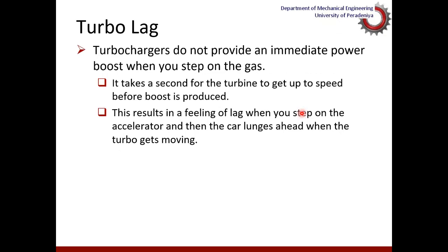And one of the issues with turbocharging is the turbo lag. Turbo lag is more or less the delay in response. Now, these turbochargers or superchargers are made using mechanical elements. Therefore, there is a certain degree of inertia within the system. And due to that, the system has a certain time constant or delay in responses. So that delay in responding to the driver input is called the turbo lag.